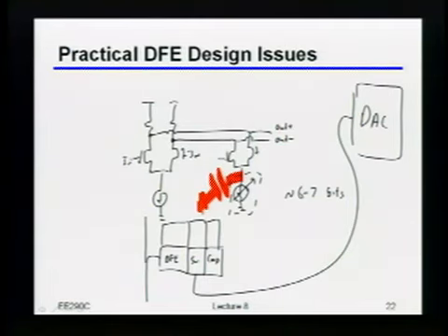And this is an issue I think I may have mentioned in the past. If you look at a lot of very, very high-speed designs, this is indeed the type of thing they end up doing. In fact, even this tail current source, if it ends up being big enough compared to your core high-speed devices, you may even take that out of your high-speed path and just route that tail. It does mean you're giving up some differential noise, or rather common mode noise immunity. But oftentimes, if you're careful about it, that may be the more optimal solution from an overall power and feasibility standpoint.